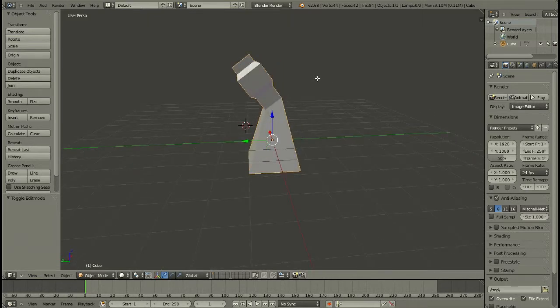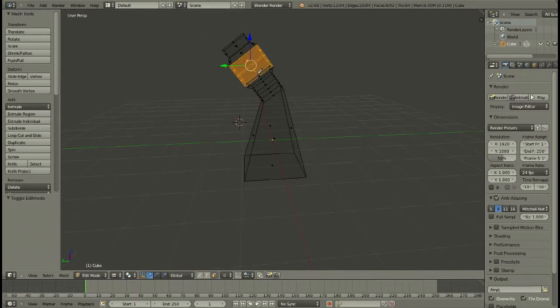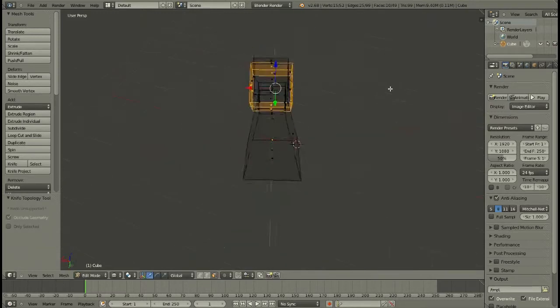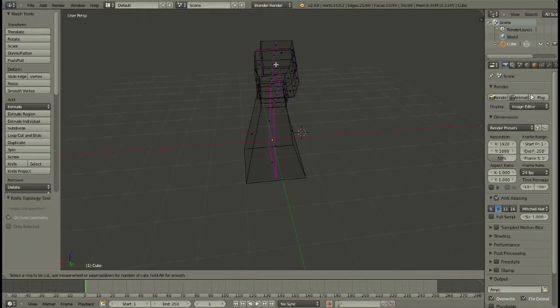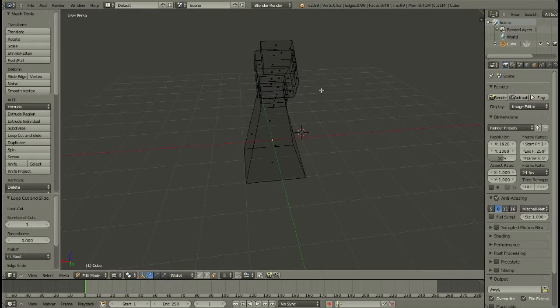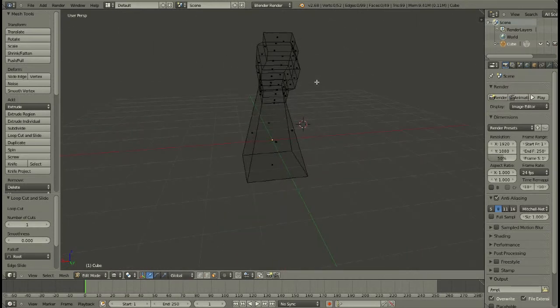There are other things you can do also in edit mode. Hit Z again, and click K. Click K, and then we click along this line somewhere, and we click down here, and then we hit enter. It'll actually add another line through there, which is useful for some things, in the case that you don't want to use Control R to do that, maybe you only need one side done. So yeah, that's also useful.